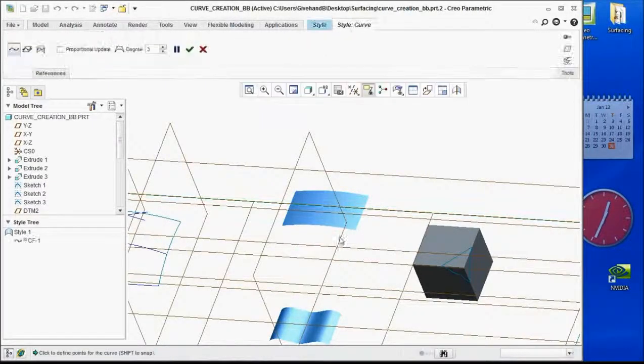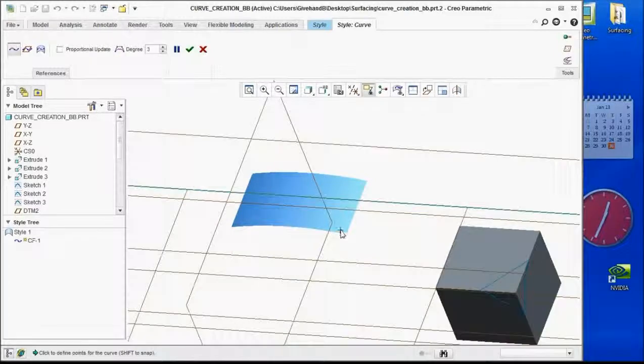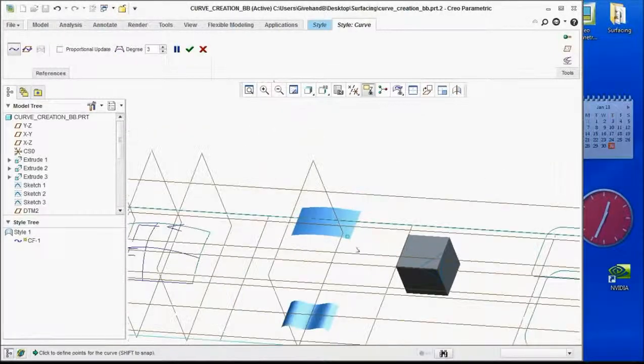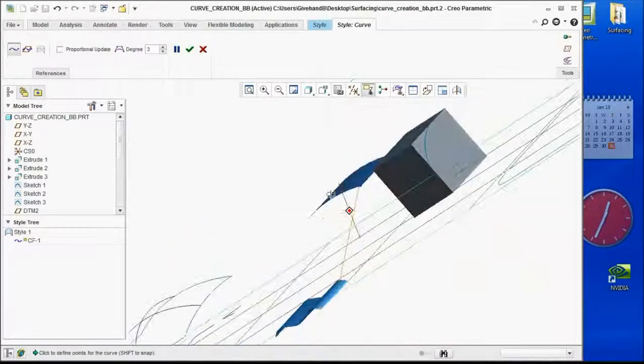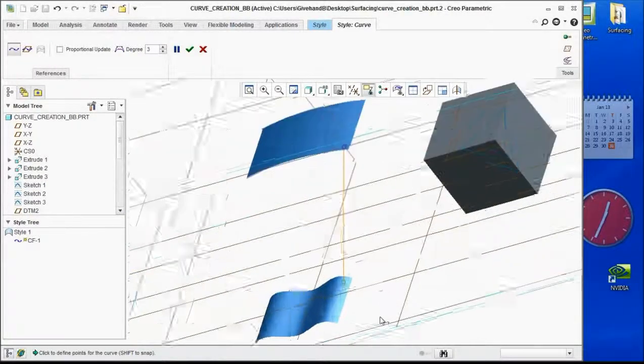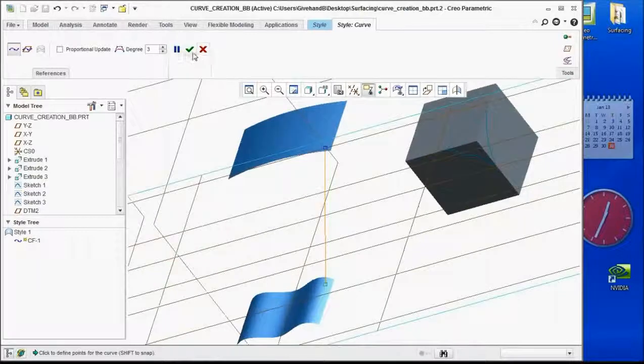And so I'm going to say I want to create a curve, but this time I'm going to hold the shift button. I'll hold the shift button here and here, and notice how now it's actually connected onto the surface. So when I'm creating this curve, holding the shift button essentially attaches the ends of your curves onto objects. And in this case, I attach it onto the surface.